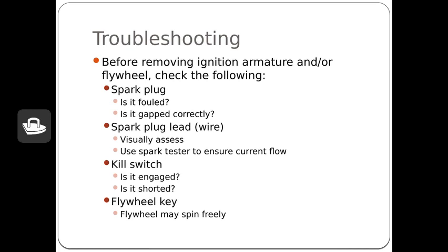And before you remove the flywheel, check the flywheel key that we talked about in the parts lesson earlier. Maybe if it's a push lawnmower or walk-behind lawnmower, did you hit a rock, did you hit a stump? Because that flywheel key, in addition to making sure the engine is timed, is also made to shear or break, to protect more expensive and more crucial parts of the engine.